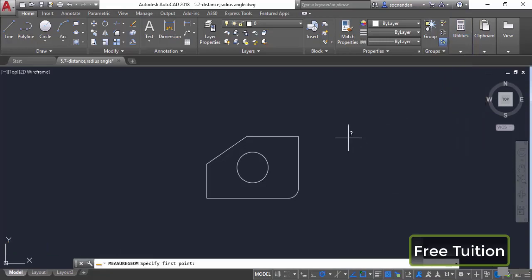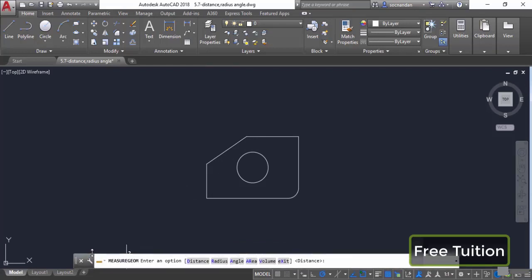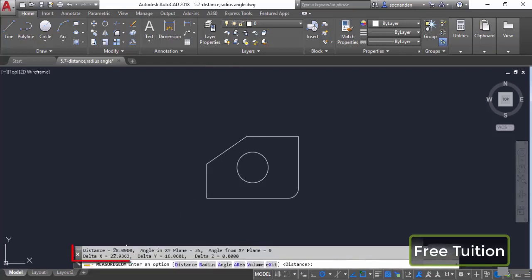Now once the command is active, click on the first point from where you want to start distance measurement, and in this case we want to start distance measurement from this point. Now click on the end point, which is this one, and we have our results over the command line. Now expand this command line, and here you'll see that the distance is 28 units. Also the angle in XY plane is 35 units. That means the angle which this inclined line is making with respect to the positive side of x-axis.